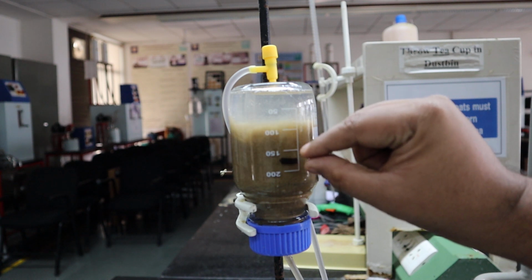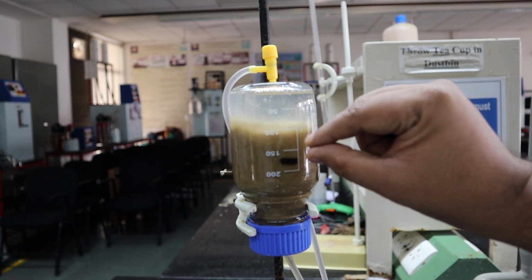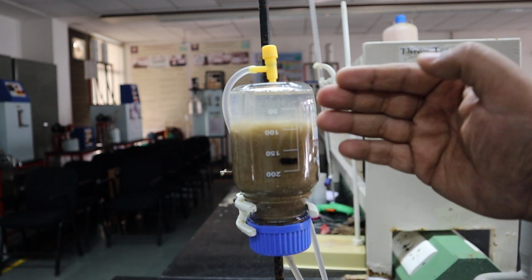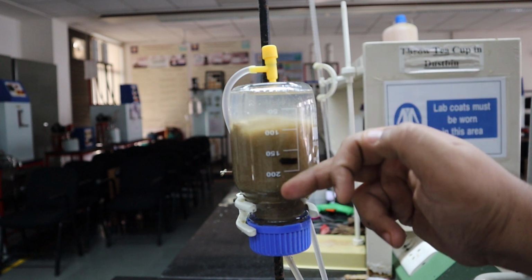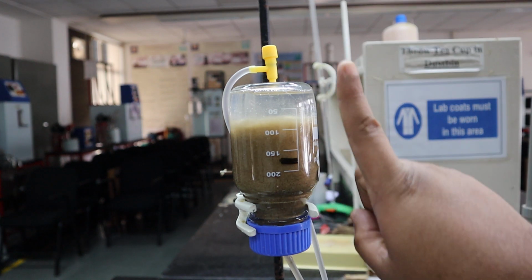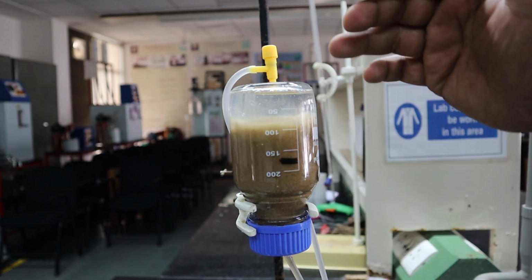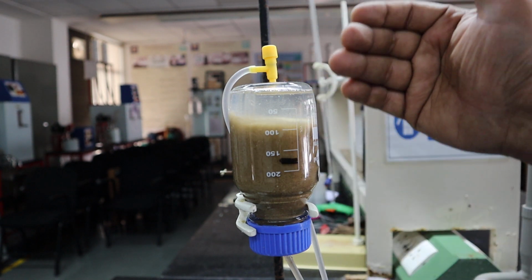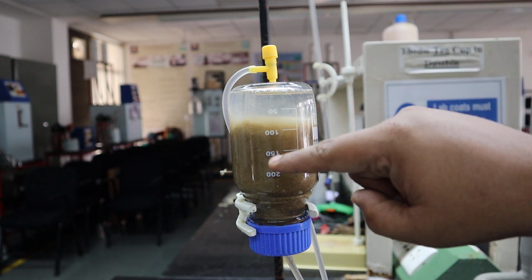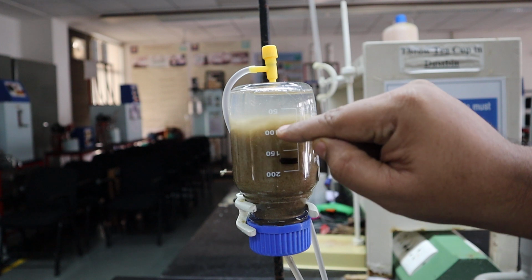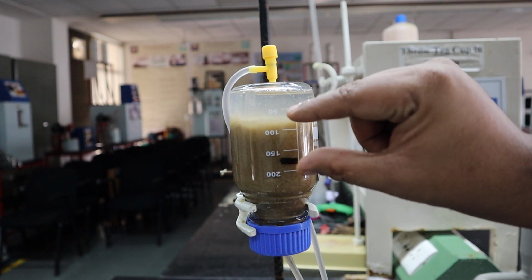As I increase the flow, the spaces between the particles are filled up by the fluid. You can see the particles are trying to come down, but the drag is trying to lift up, and buoyancy is also trying to lift up. So this is an important application of fluidization, and there are many other applications. Because the particles get separated, more surface area will be available.